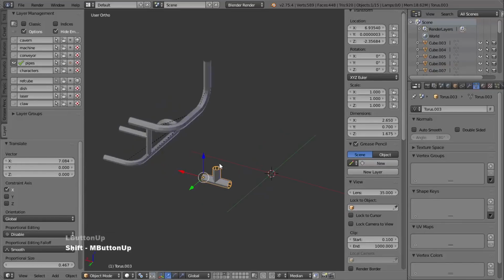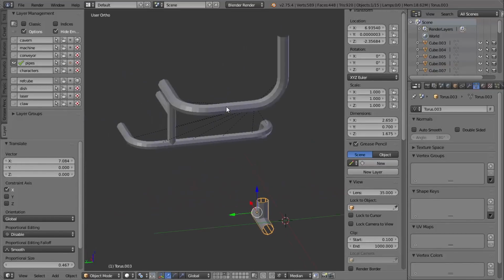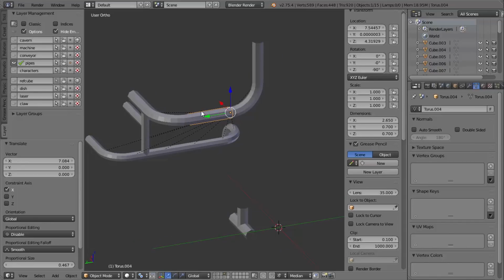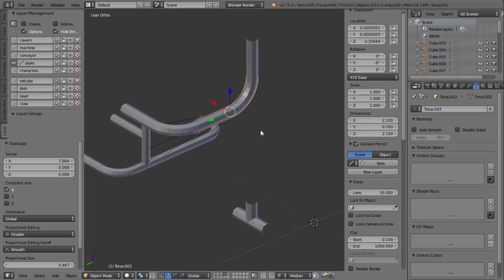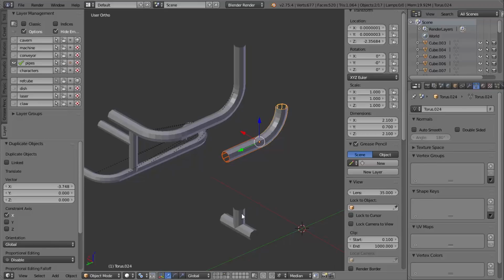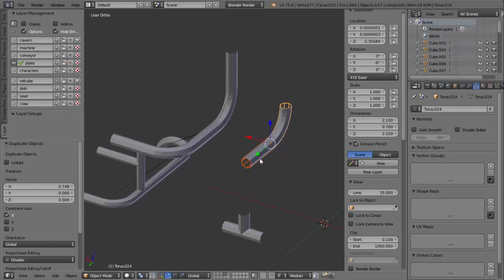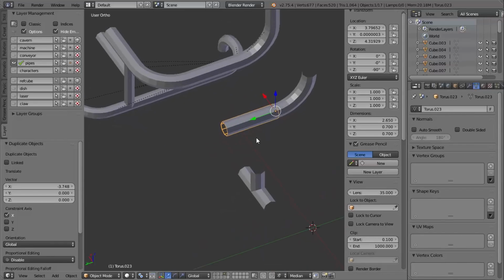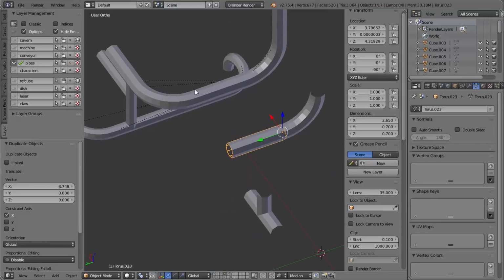And what we're going to do in this case, rather than making changes to the geometry here and then duplicating copies of that to replace the blockout geometry, what I can do instead is select the straight pipe and then the bend. And I'm just going to duplicate that and bring that out. And for these three objects, I can make changes to them and have that object data shared with the objects in this arrangement of pipes. So, for example, if I make changes to the geometry on this straight section, we can make it so that all of the straight copies here will receive those changes as well.